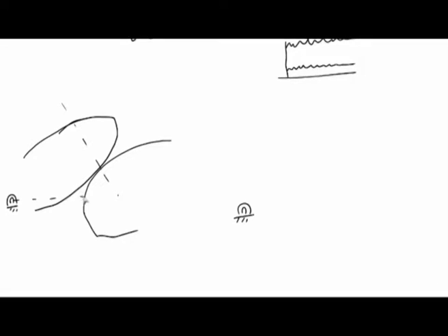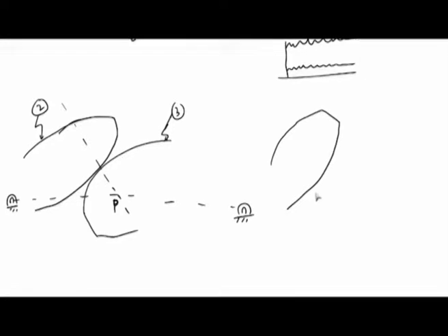So, the point P, or the relative instantaneous center between the two bodies, this is body 2 and this is body 3. The relative instantaneous center, or the point P, which incidentally will turn out as the pitch point for our gears, is at this instant located here. But let us see what happens when the engagement is at a different point.